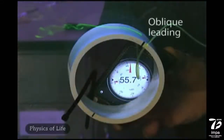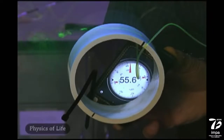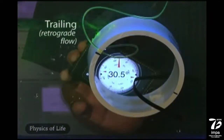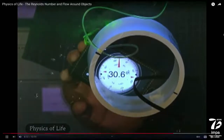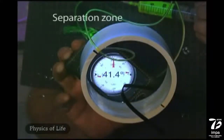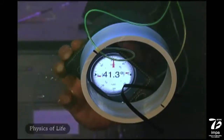At about 55 degrees upstream, flow over the cylinder is laminar and in the same direction as the prevailing flow. At about minus 30 degrees with respect to the prevailing flow, there is obvious retrograde flow from the back to the front of the cylinder. The separation zone is evident at about minus 40 degrees with respect to the prevailing flow. You can see the vortices lifting off the cylinder.